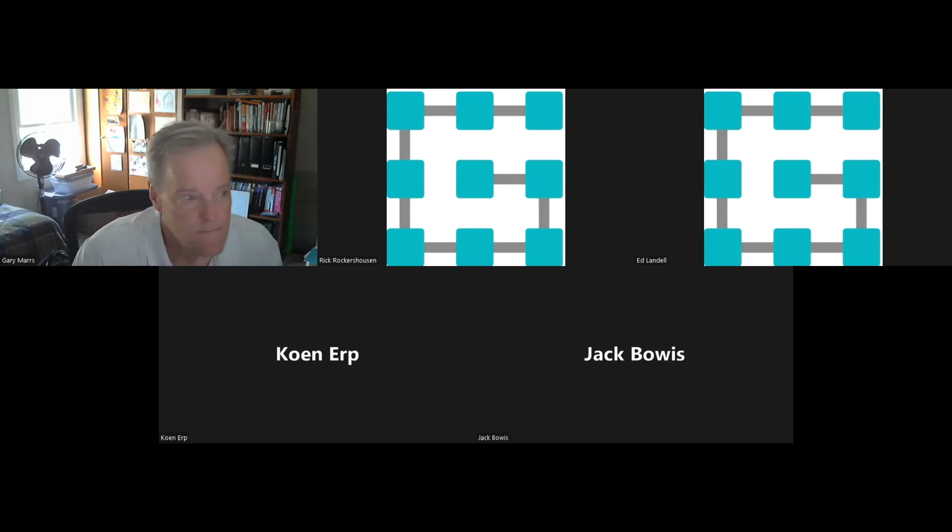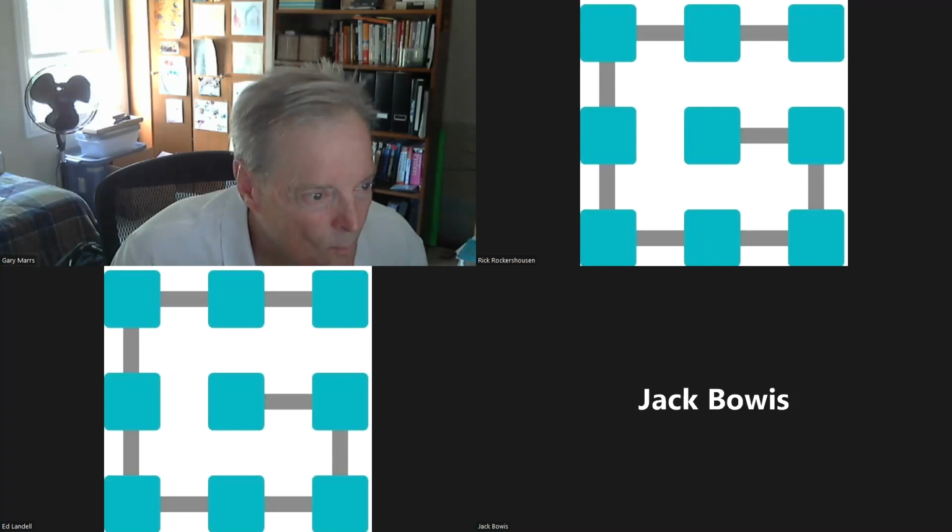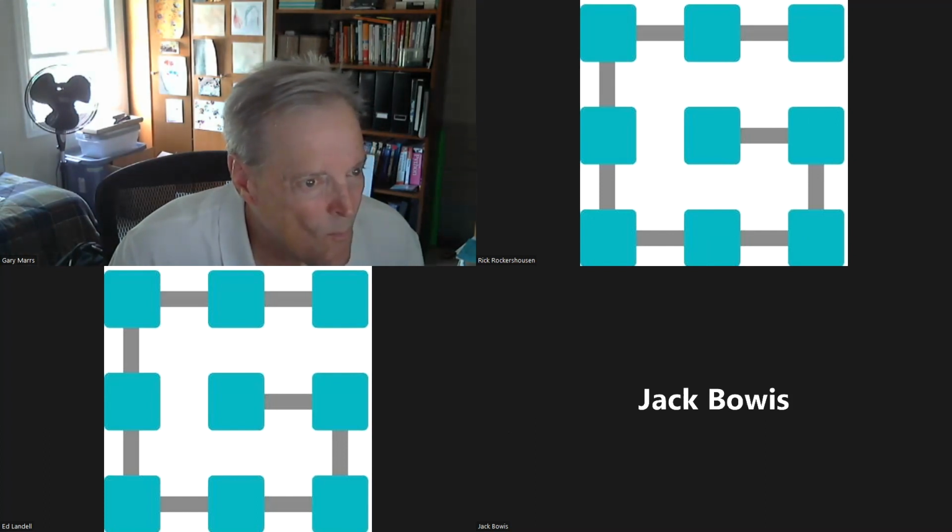Okay. So basically the conclusion here is every device is going to have a sample point. It's basically set by the manufacturer. It should be theoretically in the documentation, assuming that you have good documentation. But if the sample points are significantly far apart from each other, you could have two devices that, when both put on the same bus, don't communicate well, or cause errors to be thrown.